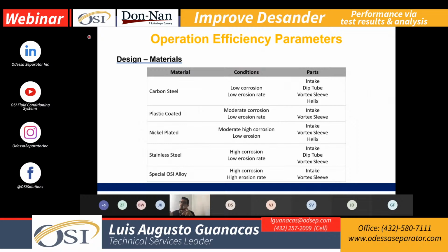In order to optimize, to achieve longer runtime, maybe if your well is in the stabilized zone, like Shivani explained, we can probably use this material. But if you're expecting really high penetration rate or really high sand production, I'm talking about higher than 200 milligrams per liter, I highly recommend you move to a different and stronger material.